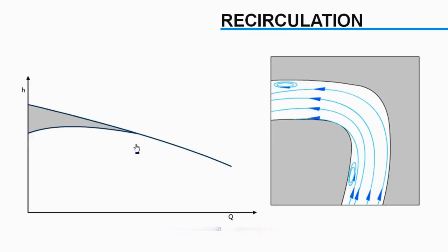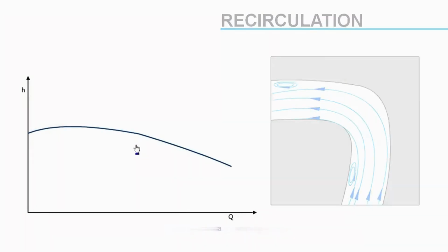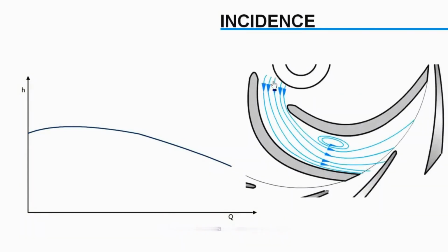If there is a difference in blade angle and flow angle, it will cause further loss. Here energy loss happens due to flow impingement and recirculation effect. This is again prominent in off-design flow conditions. So, it tends to have higher losses as we move away from design flow rate point.